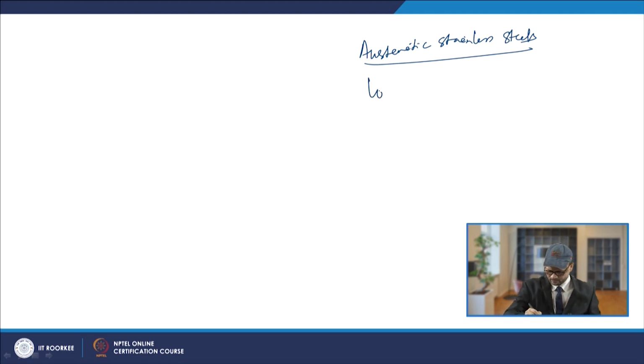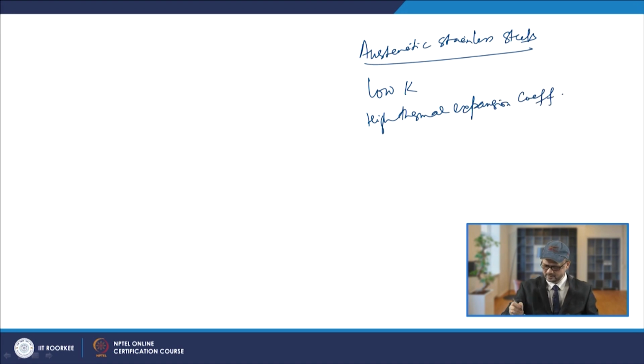So, you have low K and high thermal expansion coefficient. When they are subjected to chloride containing corrosive media, stress corrosion cracking may occur.